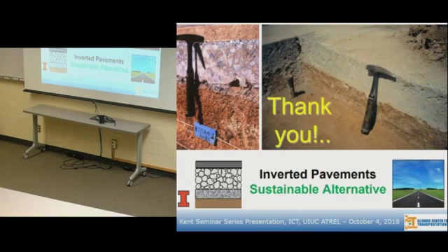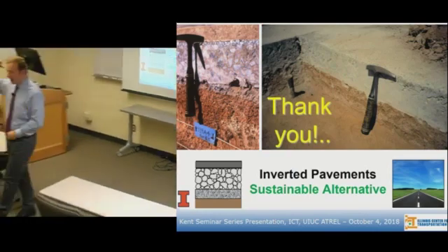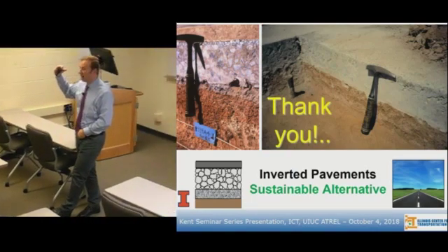That's another good question. Freeze-thaw is usually an issue with the stabilized layer, for durability, rather than the unbound aggregate layer. I don't think there has ever been a concern about freeze-thaw issues on the aggregate base. It's more the stabilized layer, if there is high cement content and large cracks opening up. But that's an excellent point. Even in that case, if you go back to some of the semi-rigid designs, like the heavy-duty cement stabilized base courses they built in China, which has been a classic approach, under asphalt concrete, putting a high percentage cement stabilized base, of course that has very drastic consequences, which are large cracks coming into the asphalt.